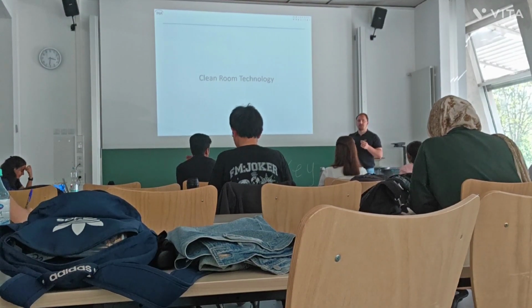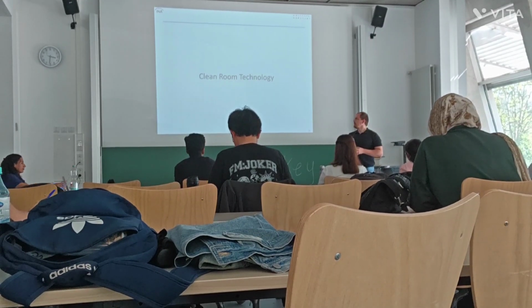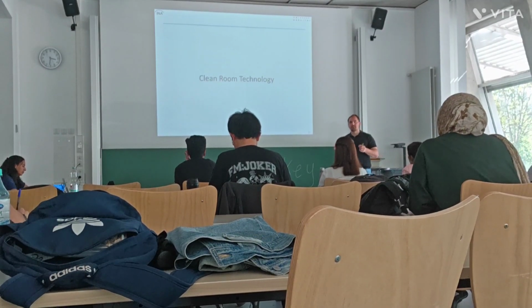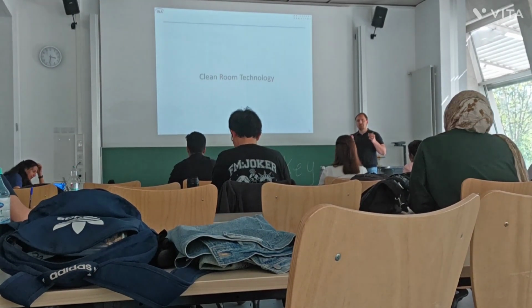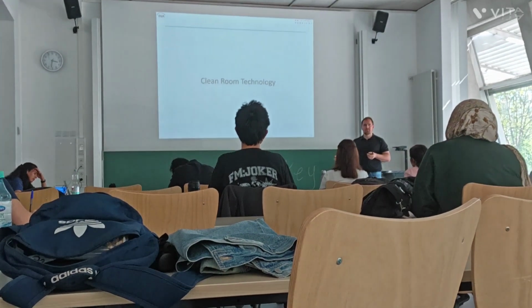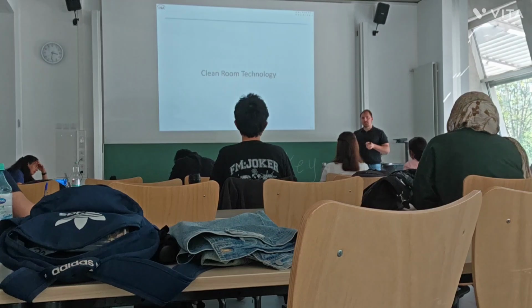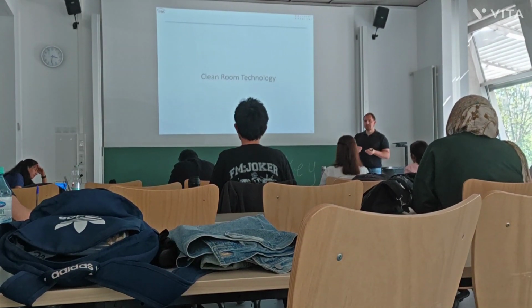But it's not only the air we are controlling, not only the amount or the density of particles, it is also stable air conditioning. So the temperature, because as she already introduced, the etching is strongly dependent on the temperature itself. When the temperature is higher, and of course here in winter we have -5 and in summer about 20, 25, the etching rate is strongly higher. It means the process is working on different days in a different manner.